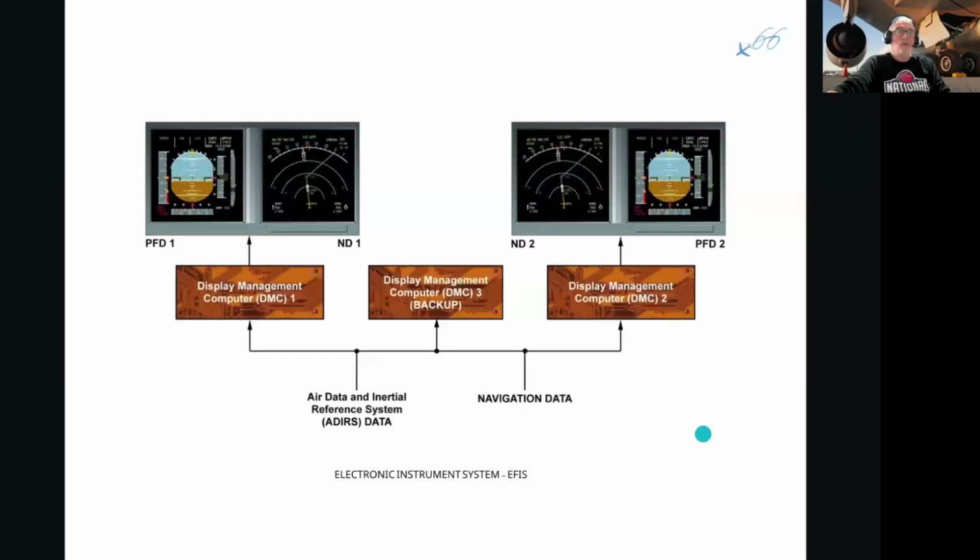Okay. Those display management computers not only work for the ECAMs as symbol generators or graphics generators, they also take the navigational data and process it and provide the pictures onto the screens.